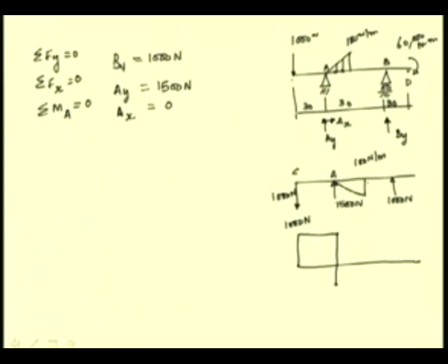Now, for this portion where we have this uniformly varying load, since the load curve is linearly varying, the shear curve will be varying with 1 degree higher, that means it will be quadratic in nature, and at this point it will rise by a value equal to the total area under this curve. So, let us draw it.